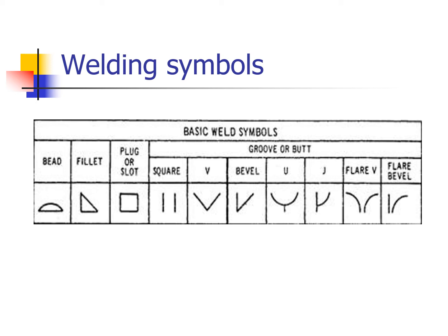and that is telling you how I'm finishing the sides that are being connected. In a square, and the symbol for that is just two parallel lines, I'm basically finishing them off square. If it's a thin piece of metal, or two thin pieces of metal, I should say, generally I'll just cut them as a square. In some restoration work, when I'm working on older vehicles, I tend to just use square ends and then weld them, because sheet metal is pretty thin, right?